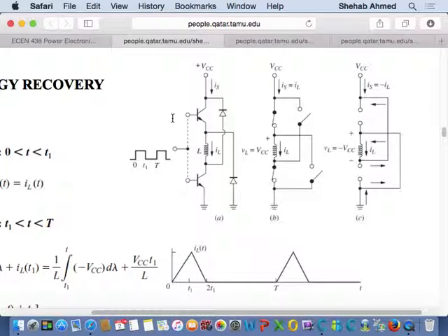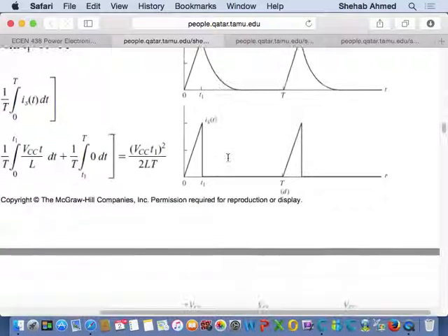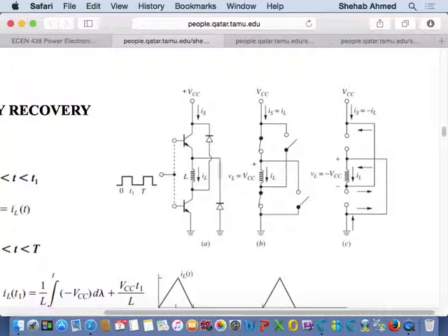In the previous circuit, you have one power device and one diode. Here you have two power devices and two diodes. So these have losses. You will have to do a detailed power budget, but if you assume they are ideal switches, then this circuit wins from a power supply, average power perspective. But then you have to go into details.